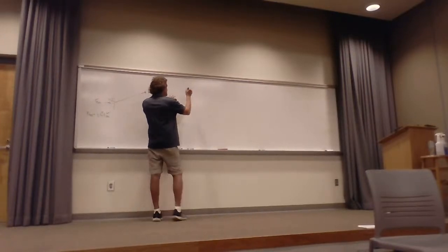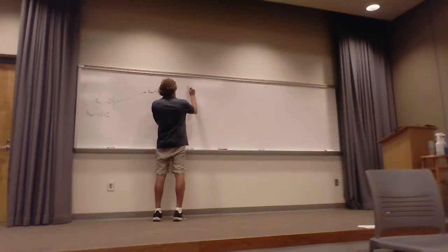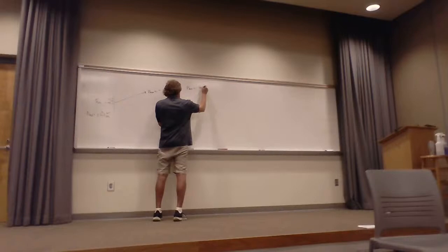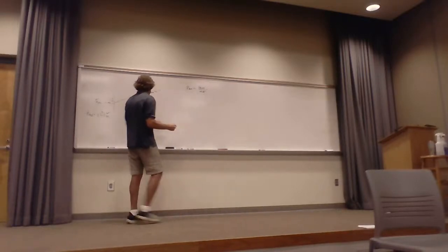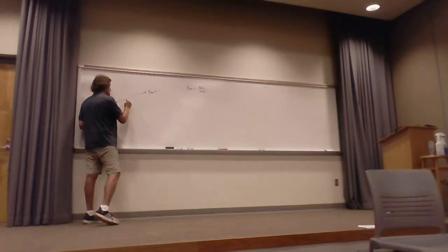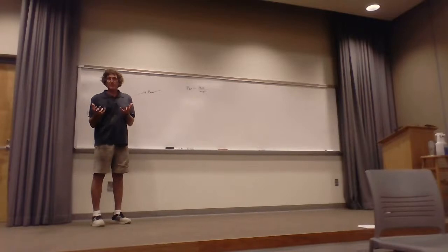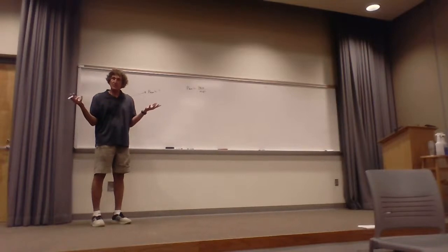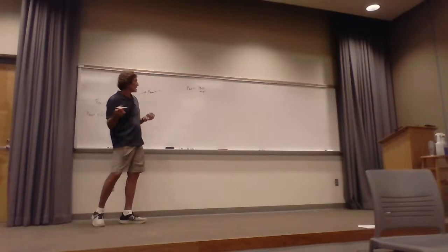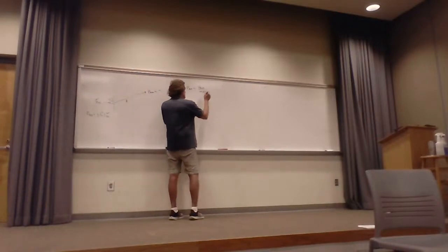I've told you before that the average power density anywhere would be the total power radiated over 4 pi r squared. That's the isotropic power density, right? There's no focusing. You put so much power in, you just divide it by the surface area of the sphere, and you've got the power density at the radius r. Now you multiply it by the gain.